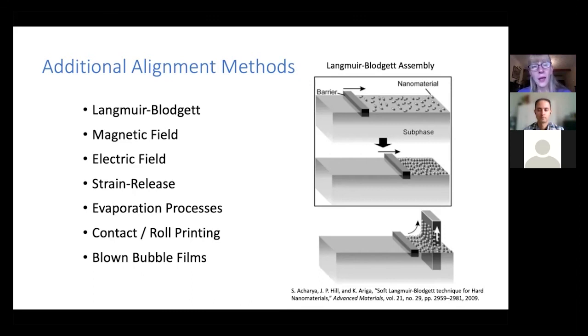And in our case too, it has to be stiff. So with regard to cellulose, unless you were able to treat the cellulose fibers in such a way as to make them stiff, this particular method would have mixed success. If you don't care so much about twisting, okay. But if you really want them aligned, it does need to be a stiff material. You'd have to process them in such a way as to make the cellulose fibers stiff.